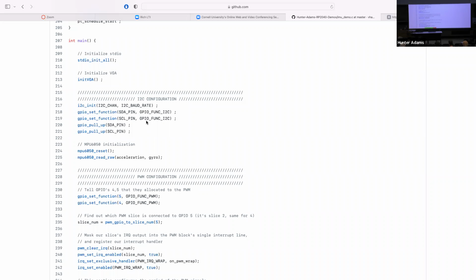Any questions about that? Yeah. I think the bus for I2C essentially looks like an RC circuit, so that it has a capacitor in it, which causes this sort of rounded edges. And I wonder why you mean, like, when we have a high value pull-up resistor that makes it softer.